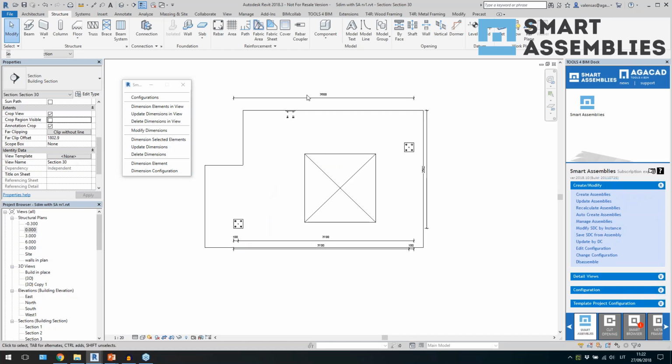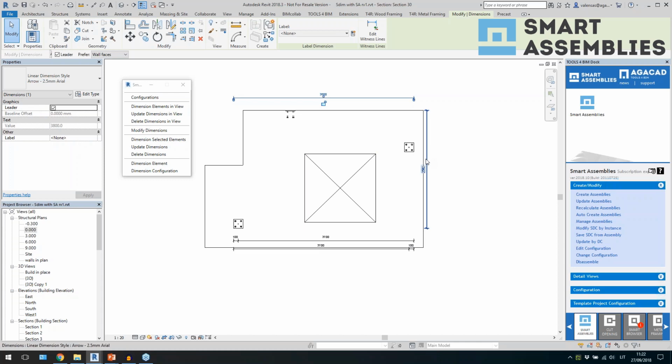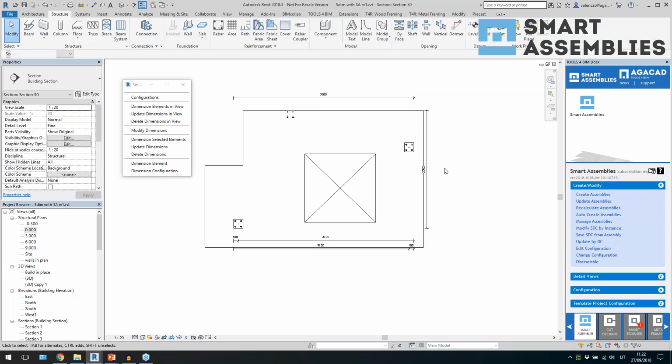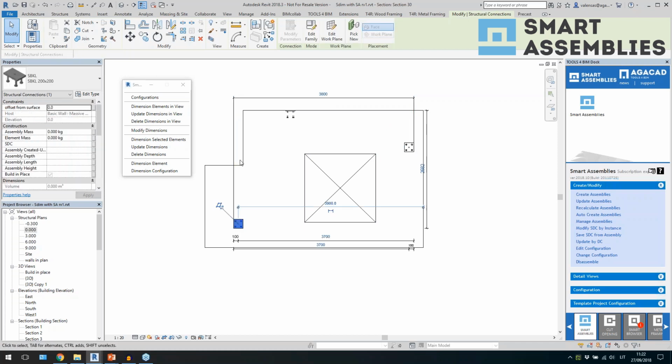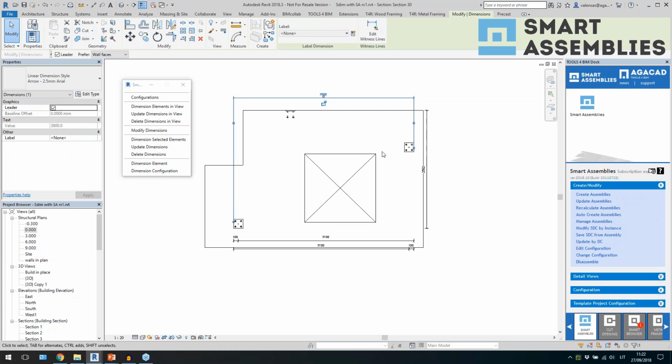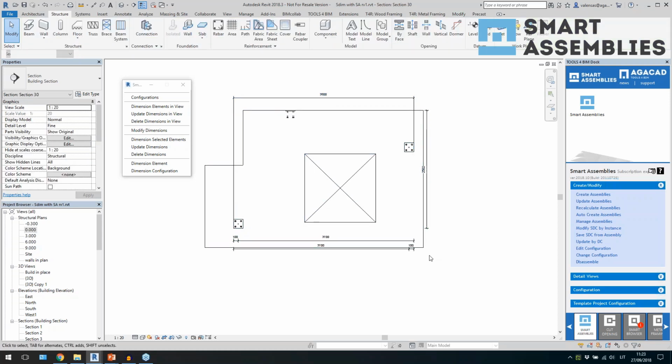You see, I have this one, and it's a total dimension, which I have in configuration, and it gives me the total distance of all the elements which I am dimensioning, because I'm dimensioning now only details. So the total dimension is giving me like a boundary of these details in the view, right?